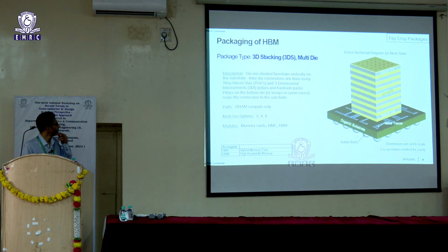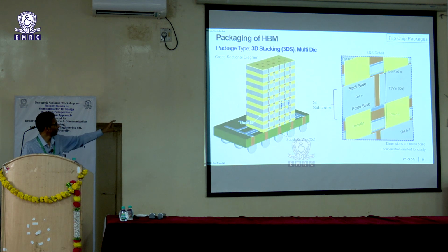And this is the HBM. As I said, you have a stack here. It's a multi-high DRAM stack. So typically the configurations are 2, 4, 8, and these days we are also talking about 12 high stack. It essentially means you'll stack 12 DRAM chips one over the other. So this is how it's stacked, and a blown up version of that is shown over there.